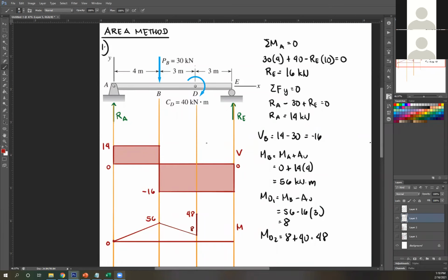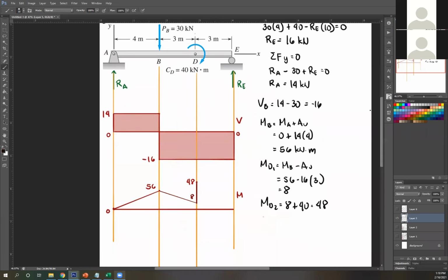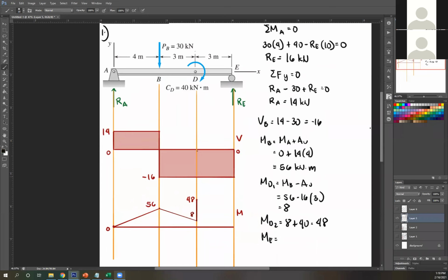Next, okay, basing here, again, you still have a negative area, so you're still gonna go downward. By how much? Let's call that ME. Okay, so don't always assume you're gonna end at 0. You still need to solve to make sure you're doing it correctly. Okay. So ME is now just, let's take this segment, MD minus area B. What's MD? 48. Well, you're gonna take the point where you stopped. I stopped at 48. Okay, so use 48.